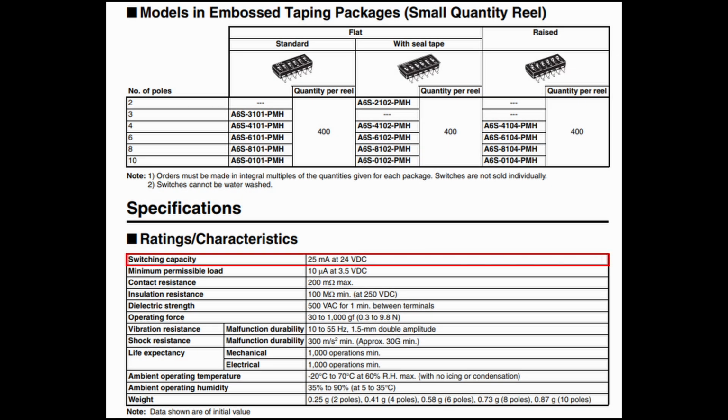Switches also have a current rating. A tiny switch usually can handle a few milliamps, perfect for an LED. But if you try to power a motor or something heavier, it may spark or fail. When you're buying a switch, always check its voltage and current rating. It may not fail immediately if you go over the limit, but it will wear out much faster and its contacts may get damaged over time. Staying within the rating means your switch will last much longer.